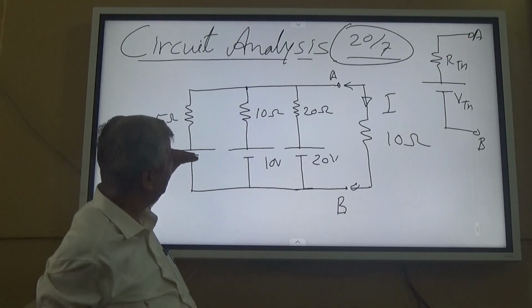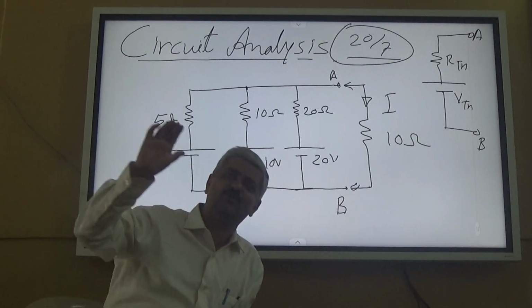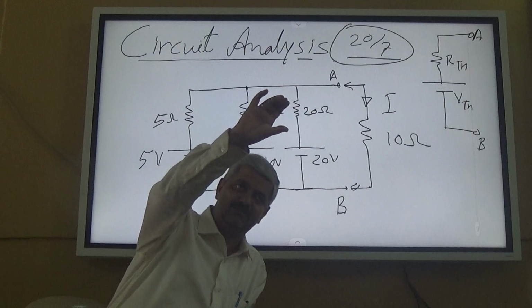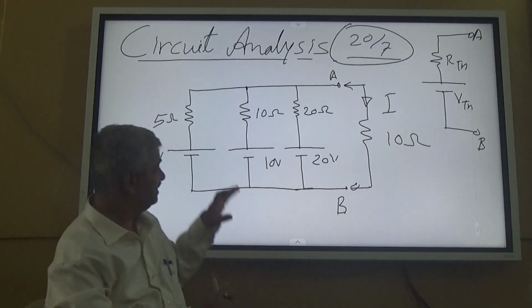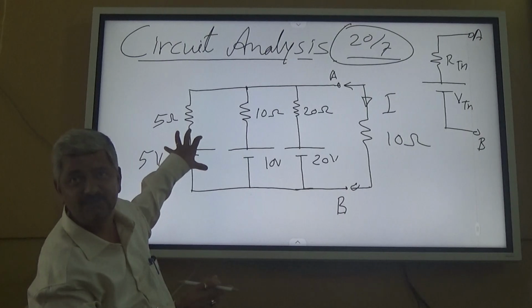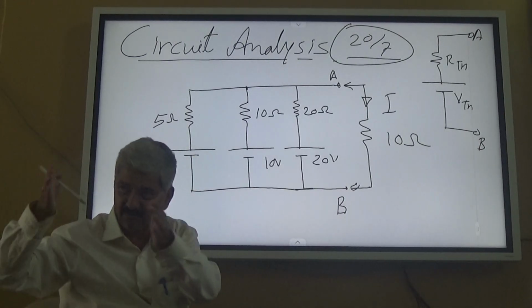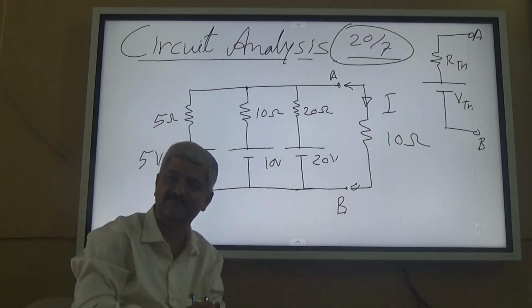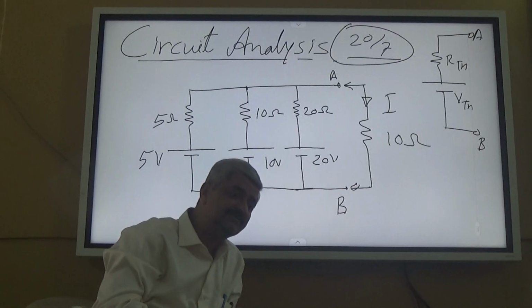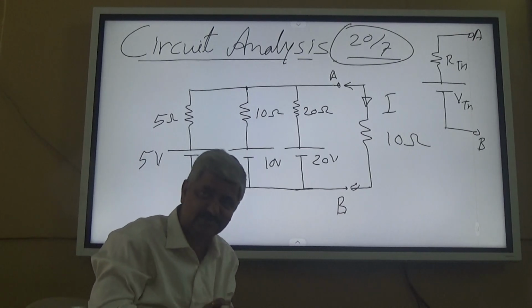I find that I connect multiple voltage sources in parallel, each with some resistance in series. Ideal, or this I can say to be a practical voltage source. Multiple practical voltage sources, ideal voltage source plus some resistance. I connect many such sources, and many times such a requirement is there. So in that case, Thevenin's theorem is not simplifying things to the extent possible.